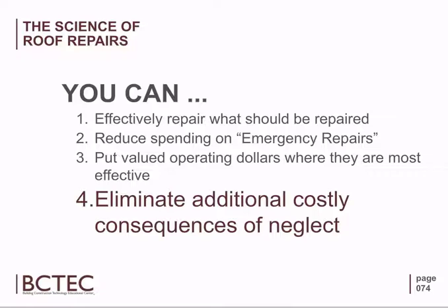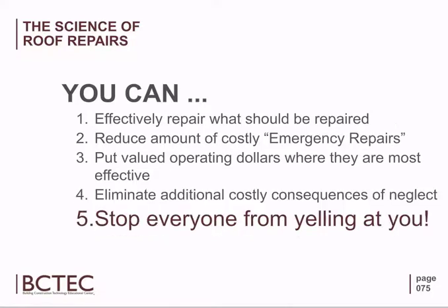And to your point, we've got a pinhole in the roof creating a leak. Well, if we let that go 3, 4, 5, 6 months, 2 years, imagine the amount of wet insulation. So what we could go put a little patch on now, done properly, solve that. Now we're looking at 300 square feet of wet insulation, major replacements, stuff like that. So if we can be really proactive, we're going to eliminate those unnecessary consequences of neglect. So that's very important.